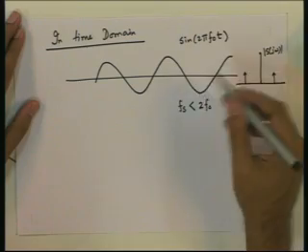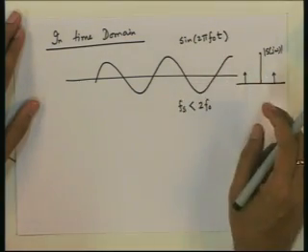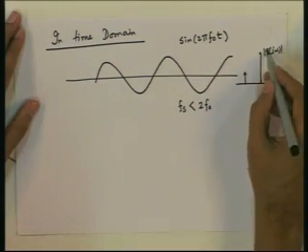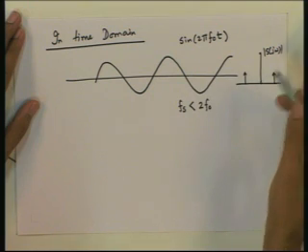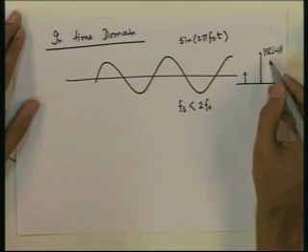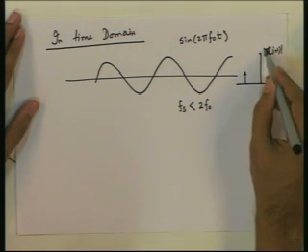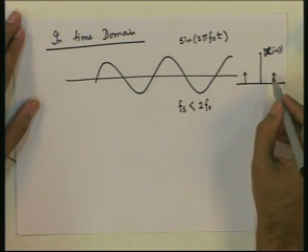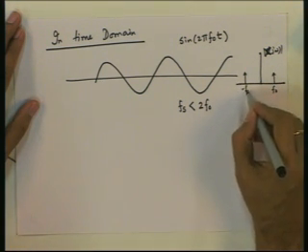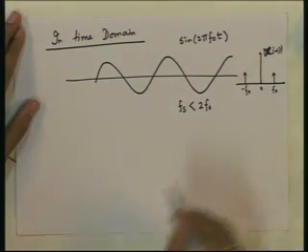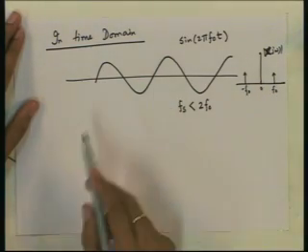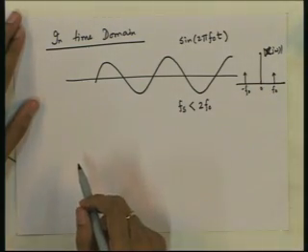The signal is sometimes denoted by x(t), sometimes s(t). With the convention we are following, we take the signal to be x(t), and this will be at f naught and this will be at minus f naught, this is 0. This is the magnitude spectrum of the sinusoidal signal, 2 delta functions.